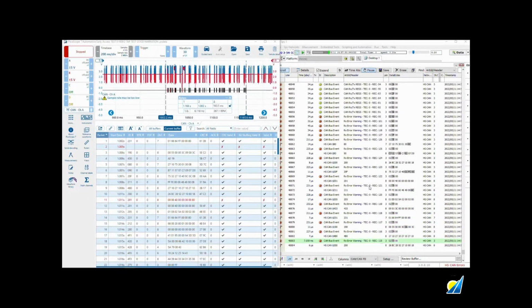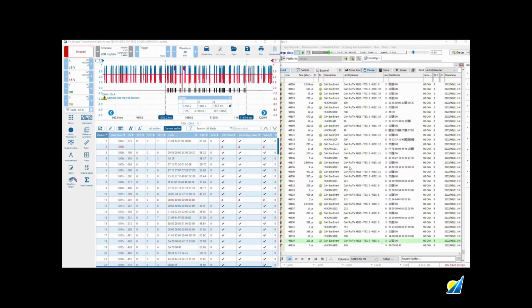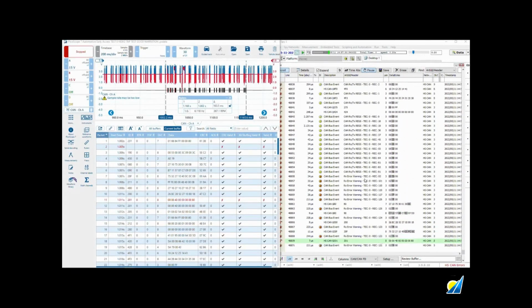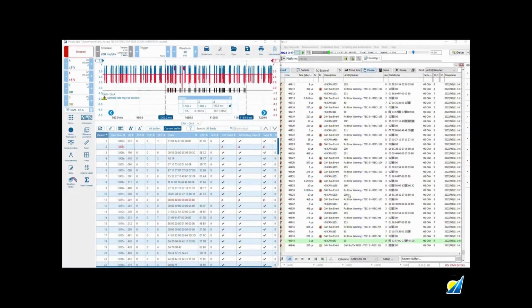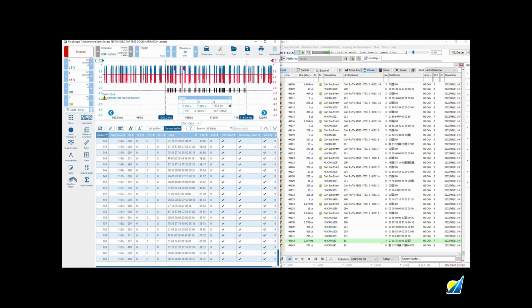This increases, and then it looks as though everything is starting to come right again, and then we decrease. And what I wanted to show here was I'd matched up, let's just quickly go back to the beginning, 231. I'd matched up the final good message, so 231 here, and then if we scroll down to the very end, where we go from error passive back to error active, where it's green, and then eventually this count keeps coming down, where we finally get to receive error 0, and then the bus is back to normal again. And I've done that here. So the last message here was 190, and there it is, and they do match.